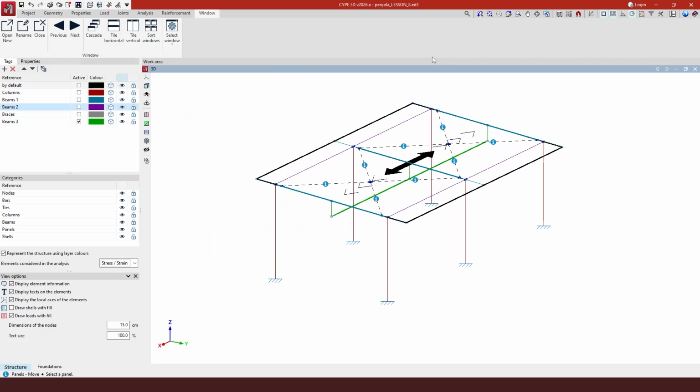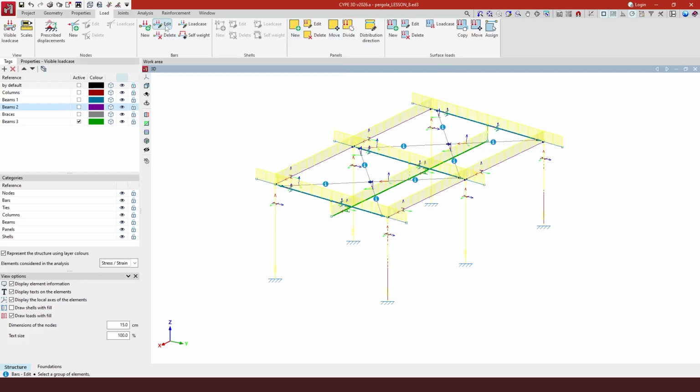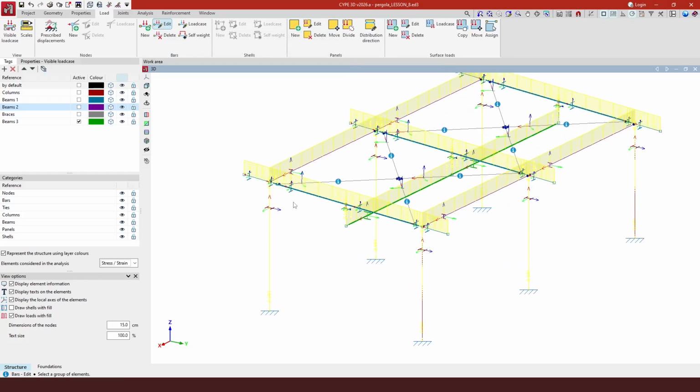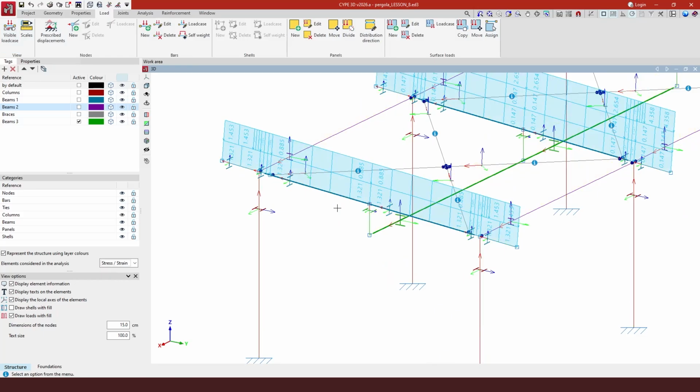and that is that if the editing that we do after coming to Site 3D from Portal Frame is too big, the stretching also stretches the loads to cover the new area. Let's make visible the load case, the wind load that the panel was carrying.